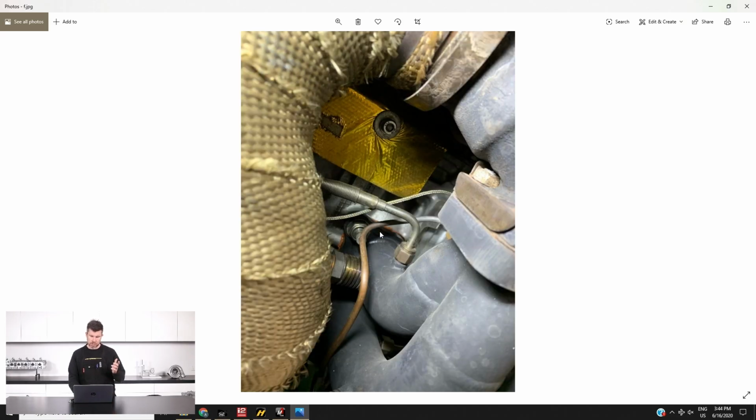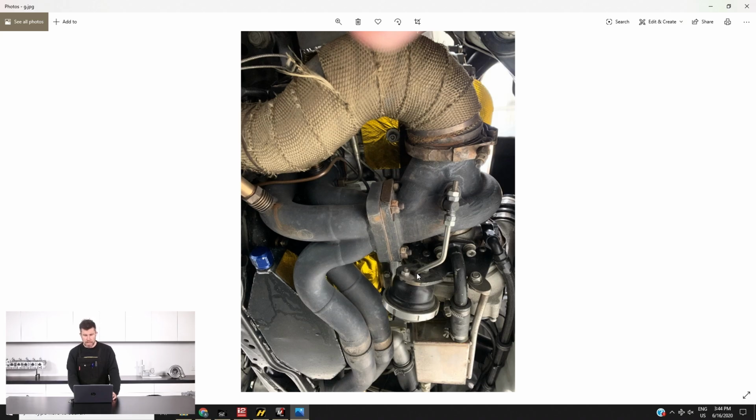This is a shot, actually I'll come to this one first. So this is a shot of the engine bay itself, and we can see again low mount turbo. This is a Borg-Warner EFR 6758 turbocharger. It's mounted on a modified AVO turbo manifold there, and this little copper line, which we can see, this is our EMAP line, exhaust manifold pressure line there. So it actually mounts just out of sight up on the top of the collector there, just welded in a little 8th BSP fitting, and it's pretty easy to connect all of that up.